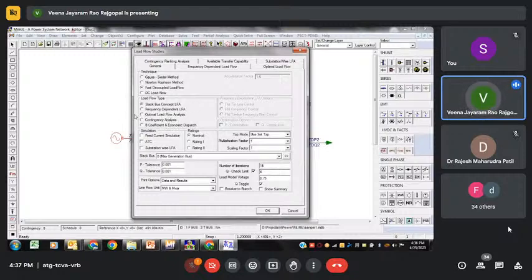So slack bus concept. Whenever we talk about slack bus, it is again a simulation concept. There is nothing called an infinite bus or a slack bus when it comes to the system. You can say the grid, or connecting to the central grid, or a grid with high inertia could be your slack bus. So when we are doing the analysis, in the actual field there is nothing like a slack bus or an infinite bus.